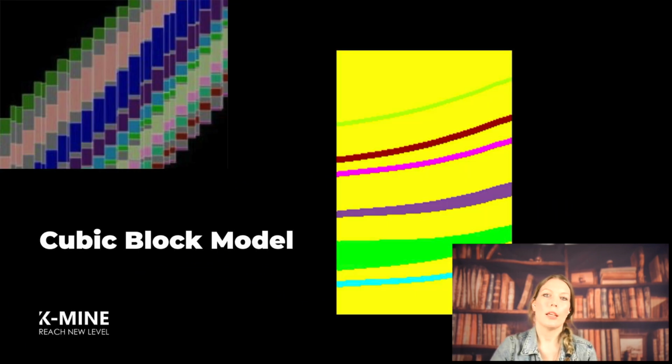The next effort in addressing stratigraphic modeling challenges involves automatically generating a block model using the defined surfaces of a layer's roof and floor. Certain software solutions tried building a cubic block model with uniform cube sizes along the z-axis starting from the grid model. However, this approach resulted in layer boundaries taking on a jagged, stepped appearance. To smooth out these contacts, the block sizes in the x and y directions were shrunk, which increased the total number of blocks and made it less practical for systems with limited computing power.